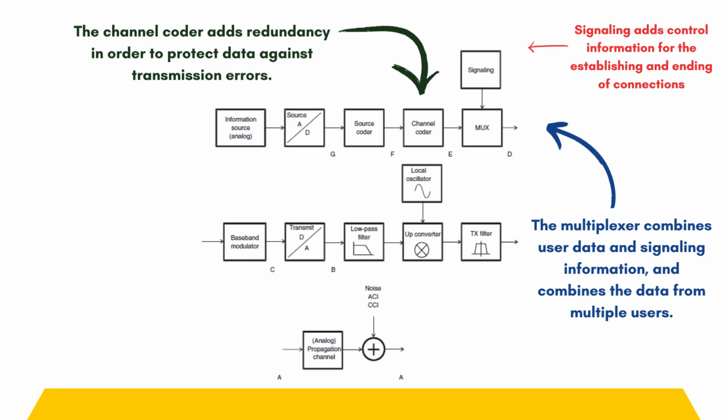So the transmitter side digital to analog converter. We do have a digital to analog converter at the transmitter side which generates a pair of analog discrete amplitude voltages corresponding to the real and imaginary part of the transmit symbols. The analog low pass filter in the transmitter eliminates the spectral components outside the desired transmission bandwidth. These components are created by the out-of-band emission of an ideal baseband modulator.